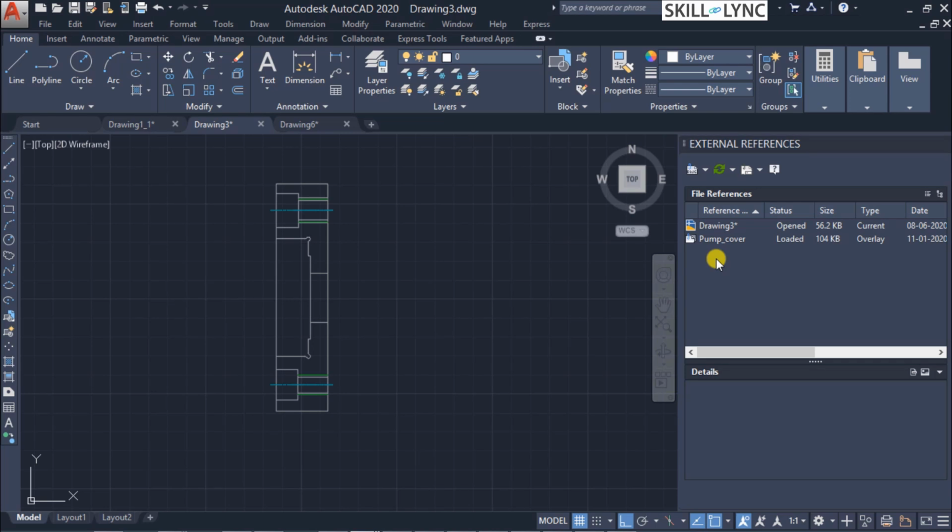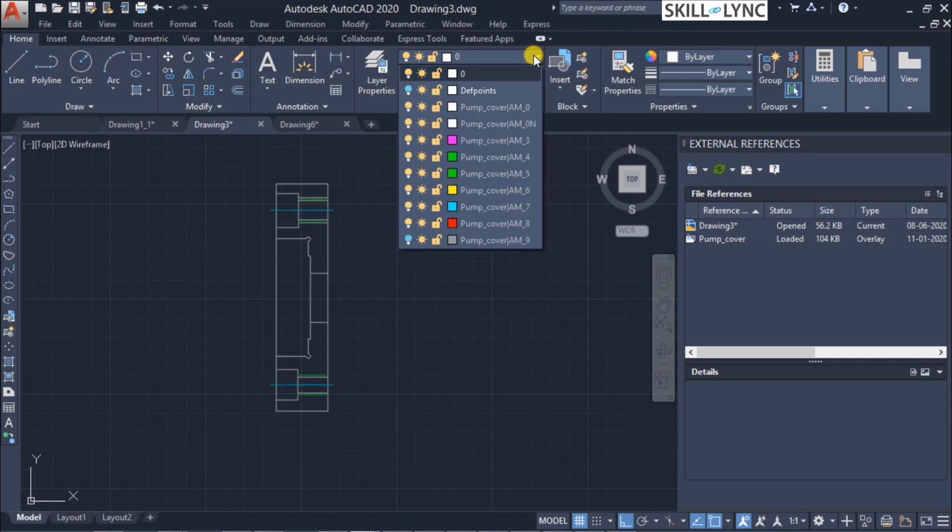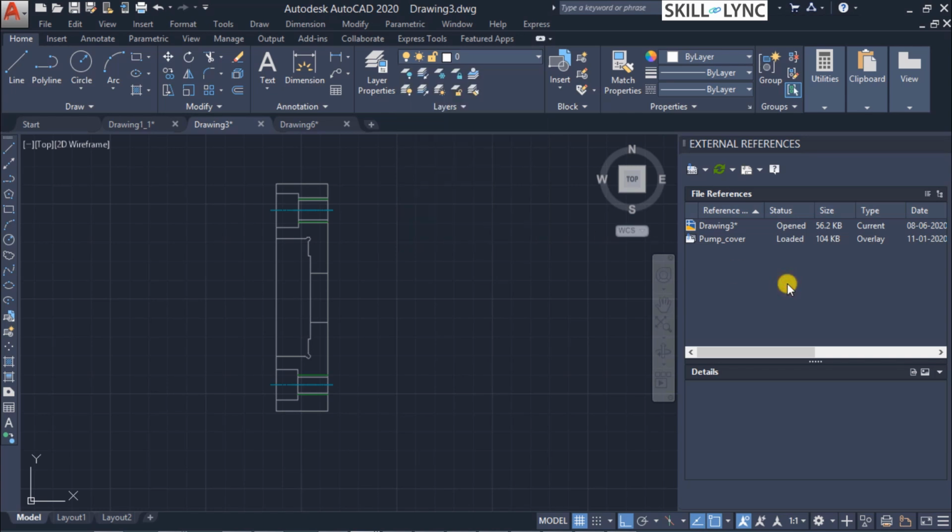What it does is AutoCAD will erase all the XRef copies, delete its definitions, and remove all the XRefs from the tree and list views. All the information such as layers, line types, everything will get deleted. You can see here now the layer information of that is also getting deleted. So you totally remove all the references of that particular drawing that you have attached from the drawing. So this is the detaching of XRefs.